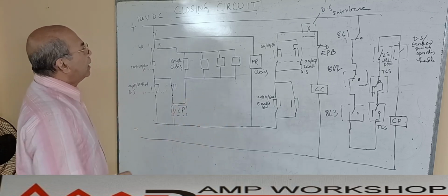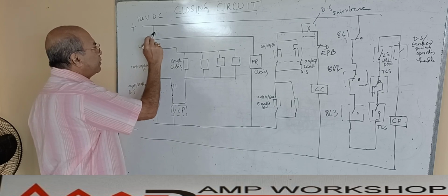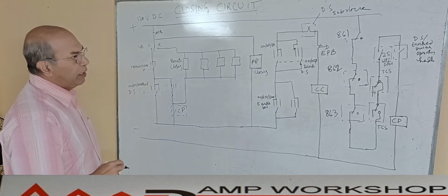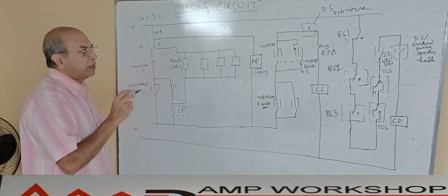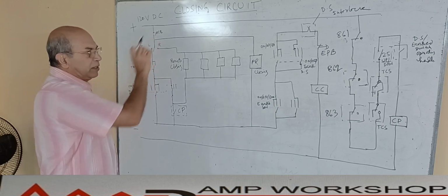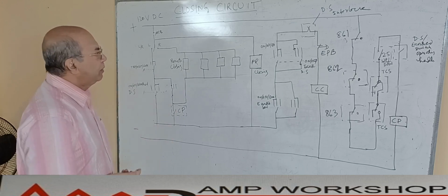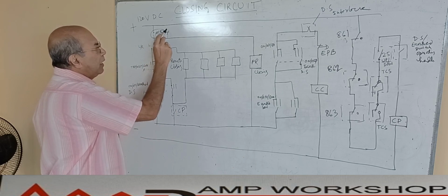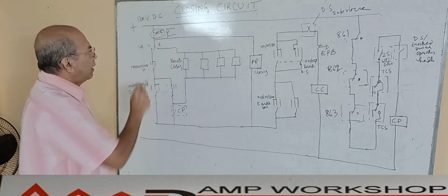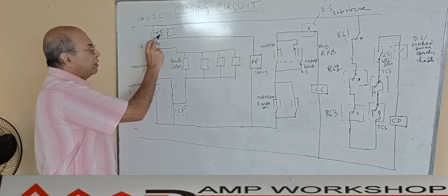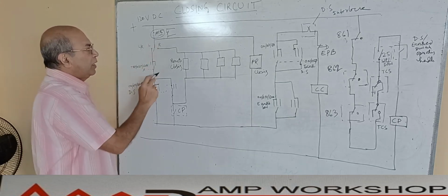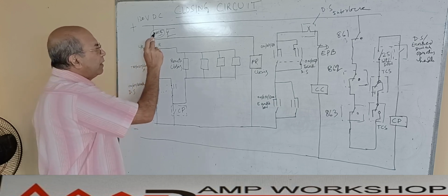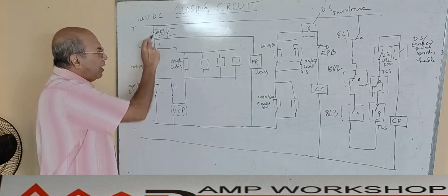The bus is running. Now from the supply, this is an MCB which is controlling the supply. This MCB is always present there. Normally for each circuit we use one separate MCB, like a closing circuit MCB and a tripping circuit MCB, and this MCB auxiliary contact we use for indication purposes at the remote. This MCB is not a simple MCB. It has short circuit protection, overload protection, as well as an auxiliary contact. That auxiliary contact we use for the status of the MCB, because that is a very vital supply.